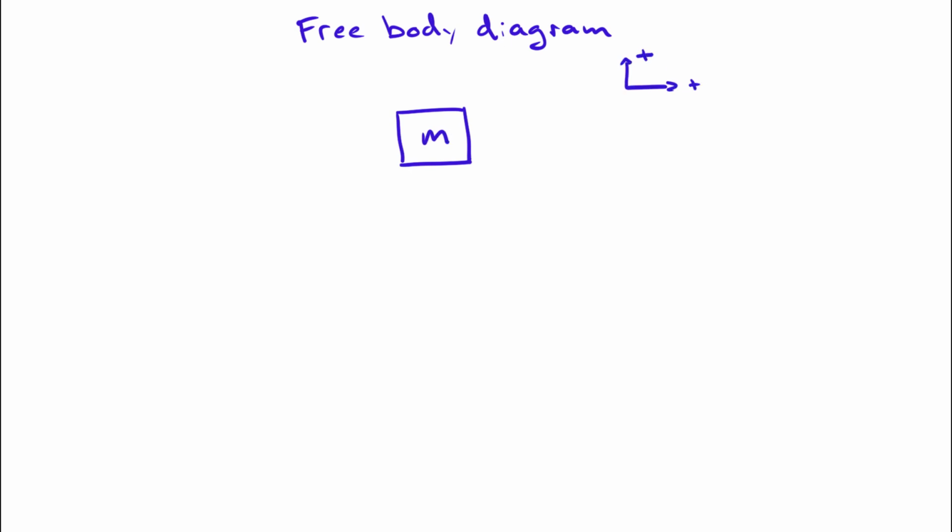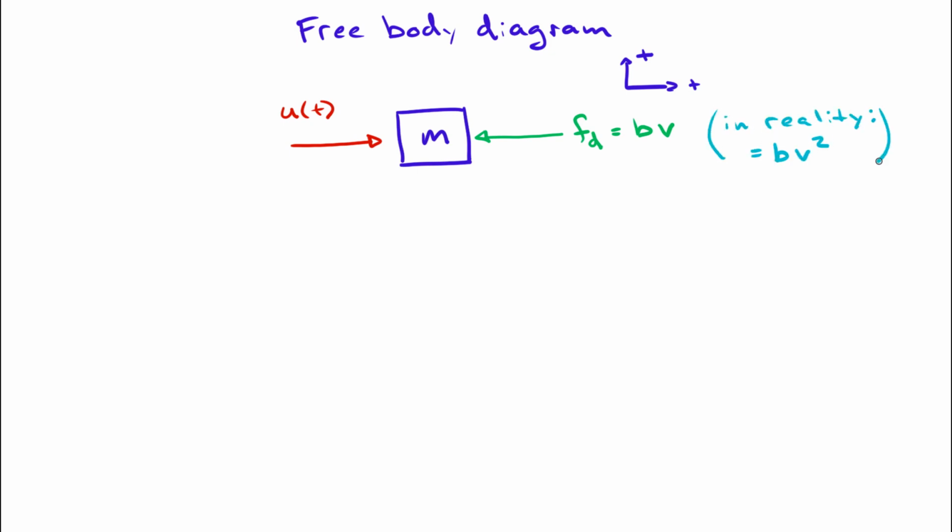in that direction. There's one force providing a forward thrust, and another aerodynamic drag force, which is often simplified as a proportional gain that scales the velocity. In reality, this is a quadratic function, but a simple linear model serves to illustrate the modeling process here. Then, we can apply Newton's second law to produce the following equation.